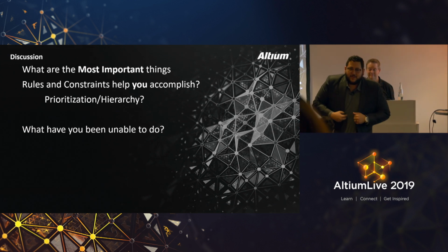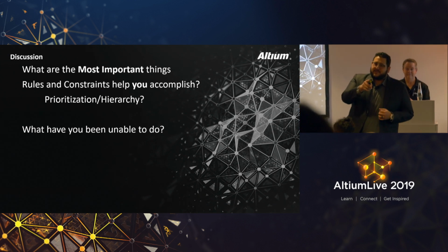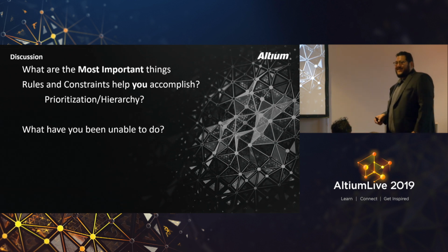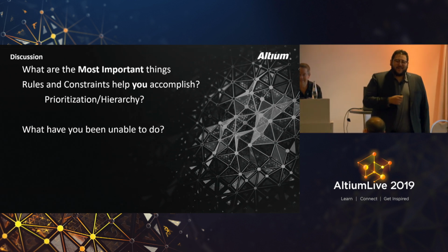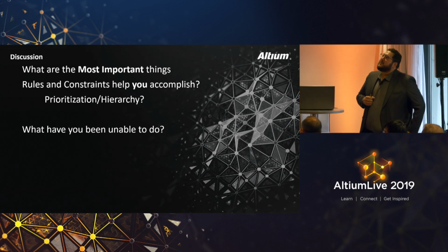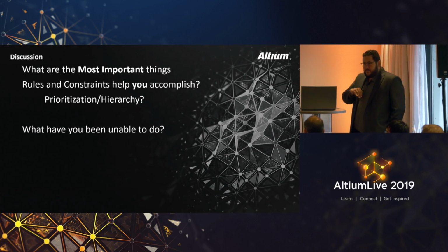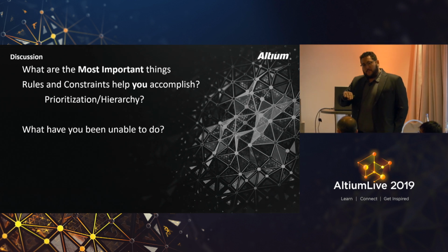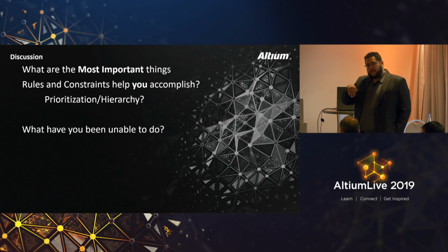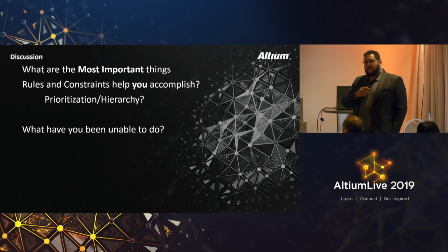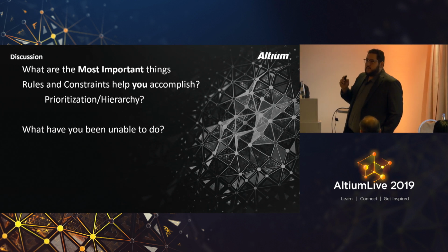Yeah, I would have one more question. Is it about waived violations? No, it's okay. Maybe it's just been me, but if you have a via stitching between two planes, or between a polygon and a plane, with another plane layer in between, and you have the via clearances, and you place them too close to each other, you will have holes like cheese, and you will not have a big enough current path through there. So is there a rule to check for a minimum path on a plane or on a polygon?